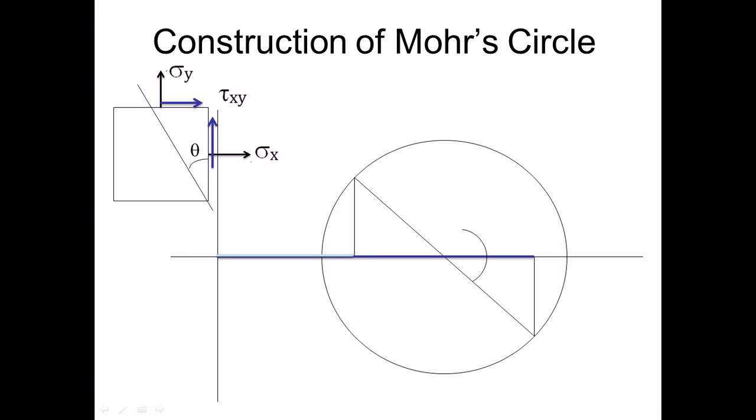This is the Mohr circle, and this is your vertical plane. From the vertical plane, the oblique plane is at angle theta degree. So if we draw angle 2 theta degree here, and draw one line, it will intersect the Mohr circle at a point. That point is called the oblique plane, and the distance from here to here is called sigma r. The angle between the horizontal axis and this line is called phi. And the horizontal distance from here to here is sigma n.